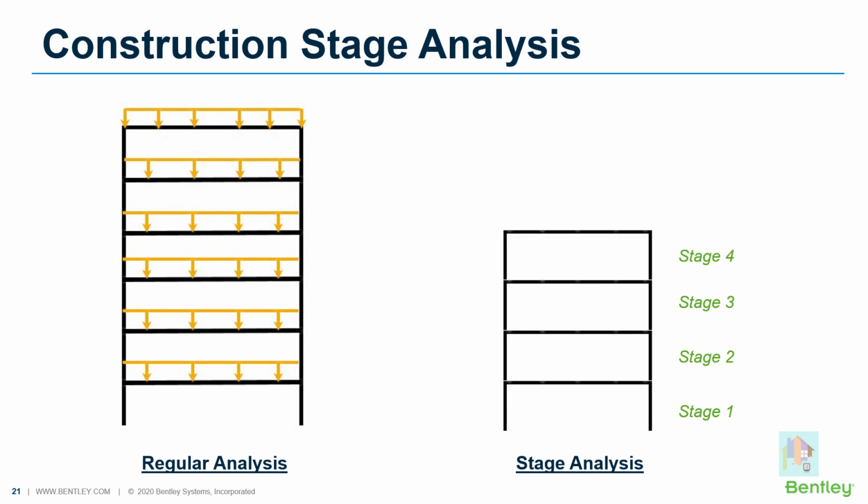These are the construction phases for each floor, and in each stage, loads are applied gradually, floor by floor, depending on the floor casting. And this can be represented like this. Also, you can notice that lower level floors are loaded for a longer duration than the upper level floors, which generates differential deformation. In short, this is the basic of construction stage.